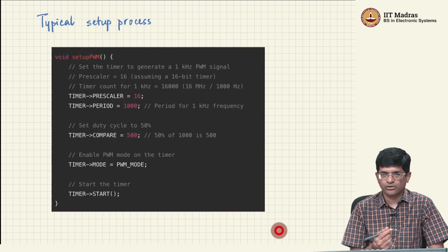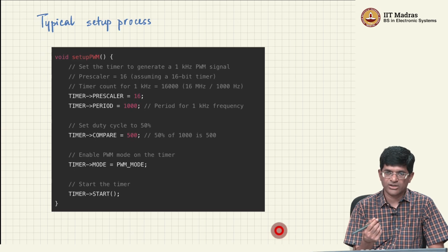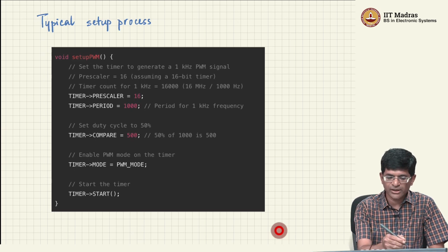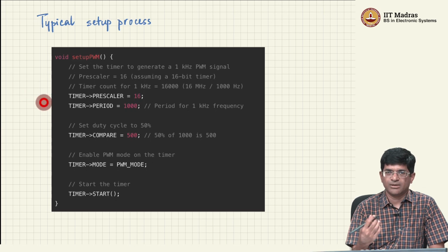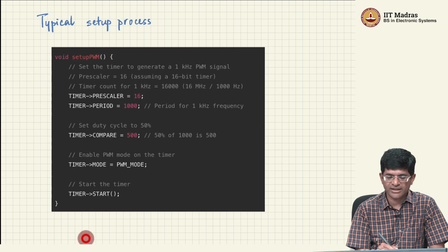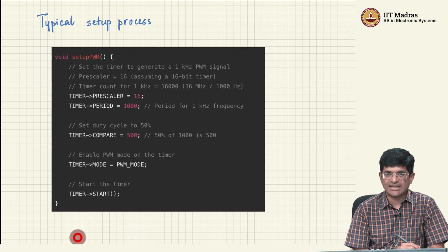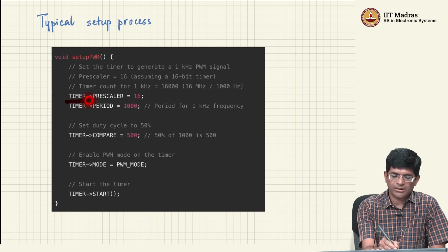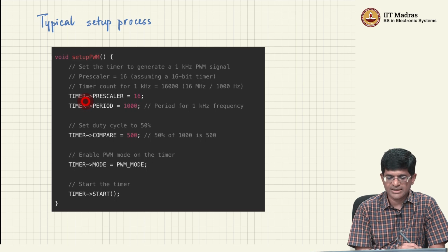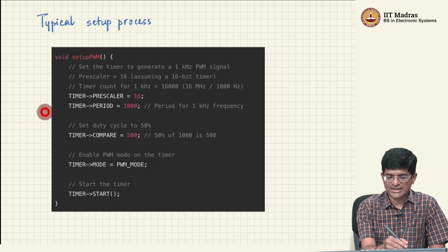Now in terms of what the code for something this would look like, right, this is the C code, it's not the Arduino level code. You would actually need to do something like this. You would basically use certain concepts that are there as part of the C programming APIs, or the software development kit, the SDK APIs that are given to you, right. You can basically define something called a timer, which is a structure in C. This is part of the HAL, the hardware abstraction layer, right, which basically says you can just set things like,